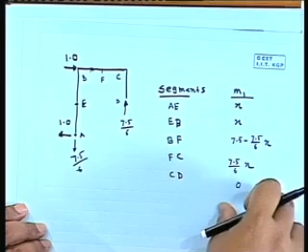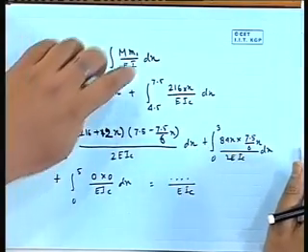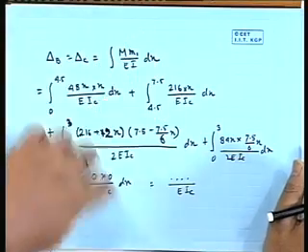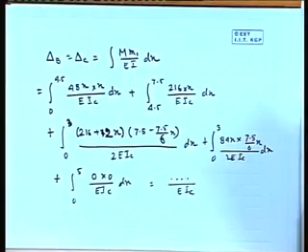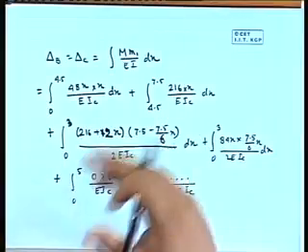That will be another set like M1, it may be M2, and in that equation it will be M2, and if you change this height, you repeat that calculation, you will get deflection at that point in the direction of the applied unit load. So in that manner any deflection we can calculate.